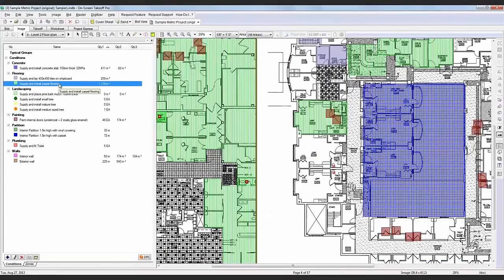So for those of you who are not estimators and don't deal with doing quantity takeoff on a daily basis, there are other programs similar to it, but this is a screen capture of On-Screen Takeoff, which is the standard here at Turner, especially here in Connecticut, for two-dimensional takeoff. If you're familiar with other programs like Bluebeam, essentially you're taking those 2D documents, created from the 3D model, and you're using basically polygons to pull quantity. If it's a scaled 2D document, you're able to draw these polygons, and it's going to give you things like perimeter and areas and counts and so on.